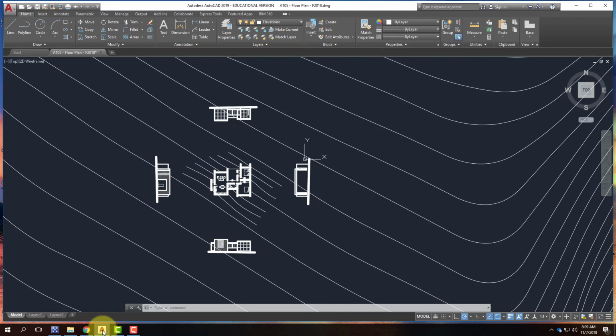And in Modelspace, when we see our drawing, it has a black background and has white lines on it. That's how we know we're in Modelspace. There's also a little tab down here. It's behind my head, so it's almost impossible to see, that says Model in the lower left corner of your page. That means we're in Modelspace. And what Modelspace is meant for is drawing things at full scale. So when we drew our house, if a wall was 6 inches thick, we drew it 6 inches. If a wall was 20 feet long, we drew it 20 feet long. So there's no scaling. Everything's full scale when it's in Modelspace.